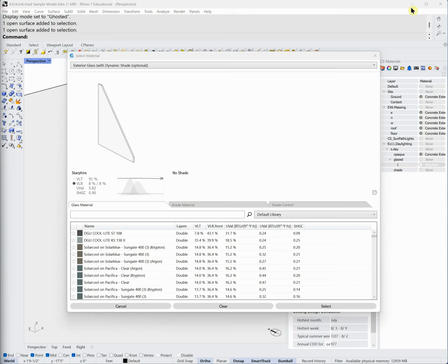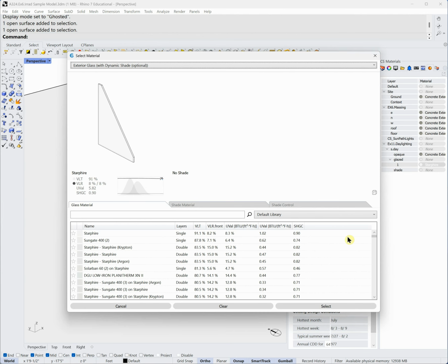So in this case, I'm going to pick something that has a pretty high visible transmittance. I have a tool in Old Westbury, and actually I probably should have found something that had like an 85, because I think the plexiglass I've got in Old Westbury has a visible transmittance of about 85. I haven't really, I want to be more systematic about how I test it. But the point is that if I'm going to be taking my cube outside with plexiglass in place, I need to simulate with something as close to the specs for that material as I can.